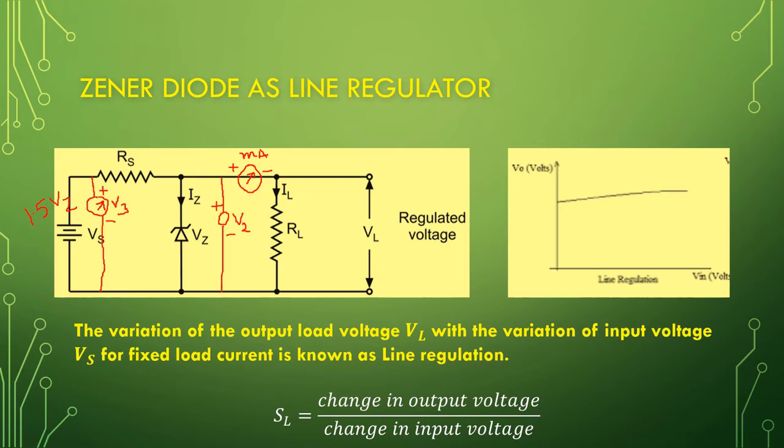If our Zener diode Vz value is 5.6, then we multiply 1.5 by 5.6 and the input is set to this value. If our Zener diode voltage is 4.7 volt, then we multiply 1.5 by 4.7 and set the input voltage Vs to this value.